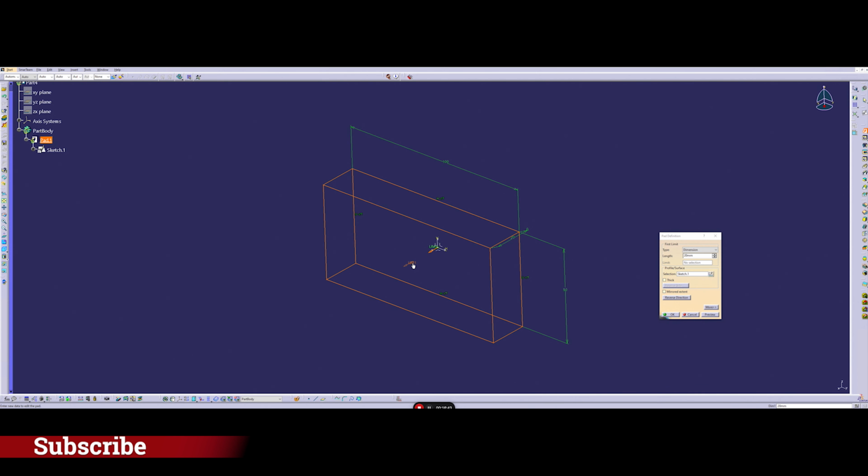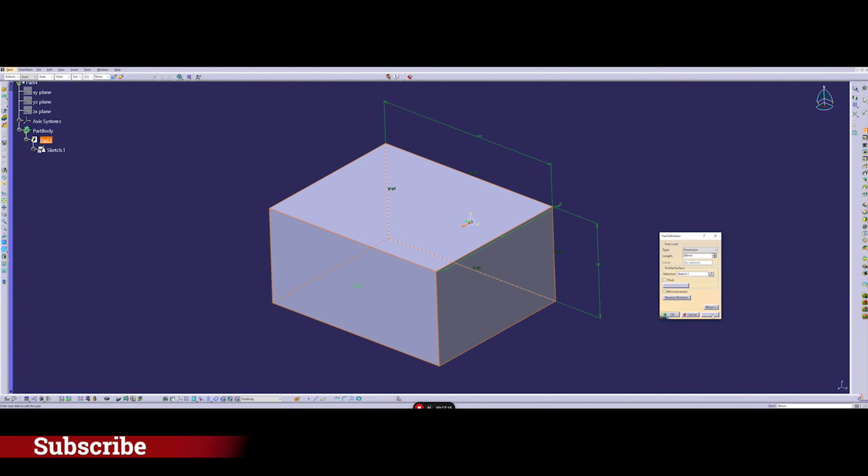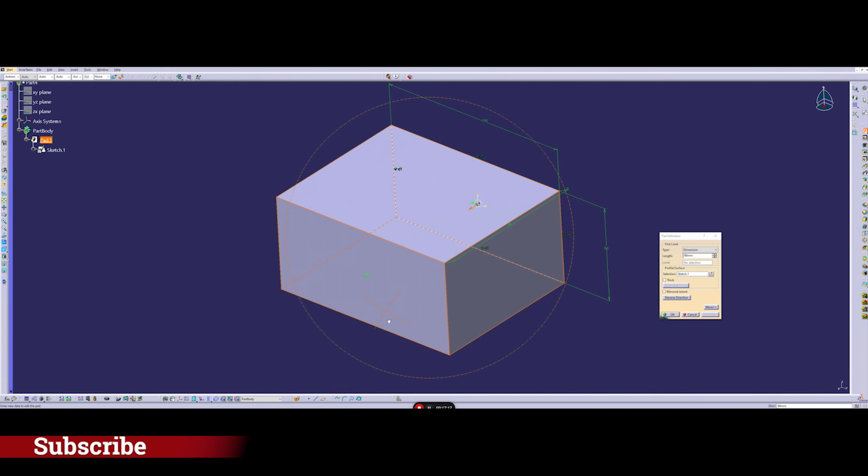With limit 1, if I select it, I can change the dimensions of the part that I want to make this pad. Either you go from the length in the window and change it from 43 to whatever, say 80, and press tab after you have the preview. Or you press tab, or you go directly and do a preview here, and you see how the model will be.